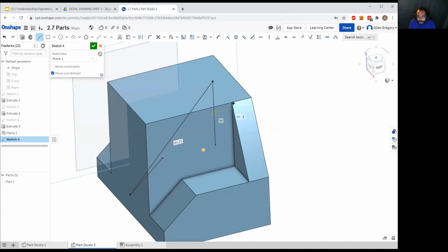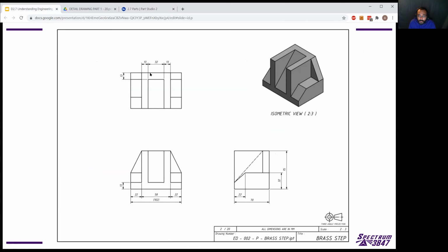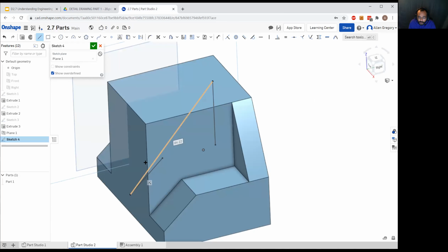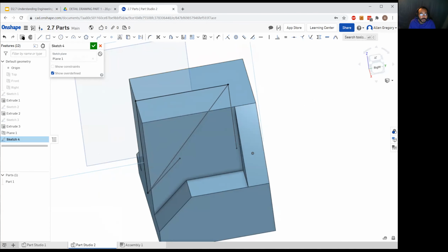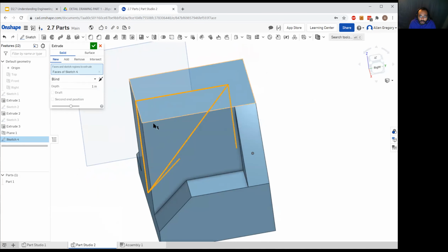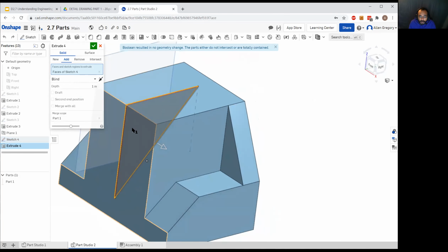And we already know that these dimensions are right because we already had that 13 dimension that we pulled from that side pod, and we had the dimension up front here that we pulled from this line. So we know those are in the right spot. I'm going to go ahead and finish out this drawing. So we have that triangle made. Now we know where it is, and we can extrude from this shape.